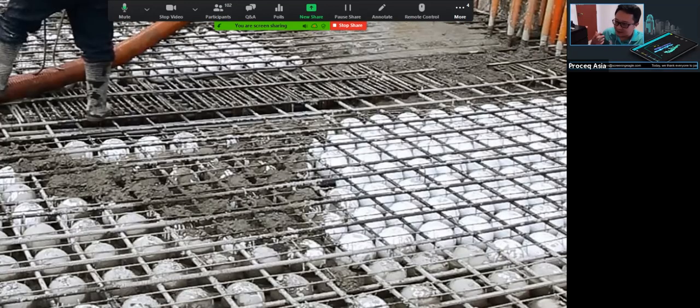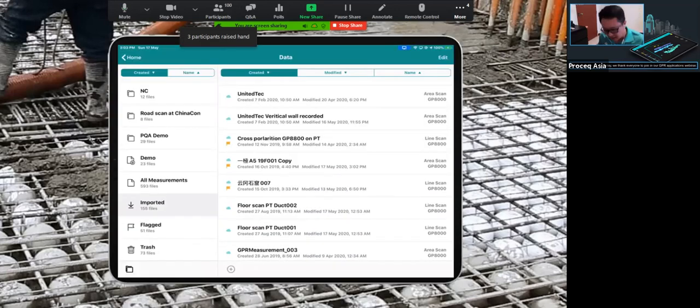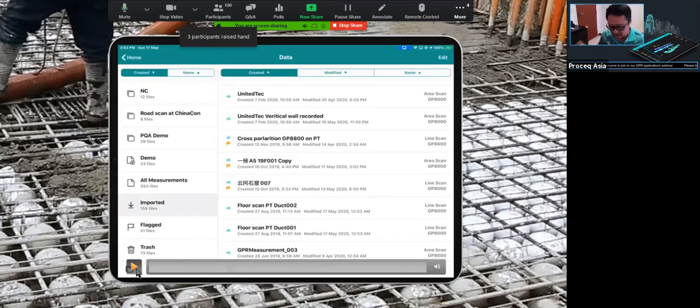And there can be another kind of hollow core. It uses high density polyethylene, this kind of ball bag inside the concrete, not only to reduce the weight of the structure, but also to give some other advantages, such as anti-noise, and for some seismic designs they also use this. Actually this result was provided by Yan Shuang in Taiwan. It's also quite common to use this kind of structure design. I also made a video to see how this result looks.